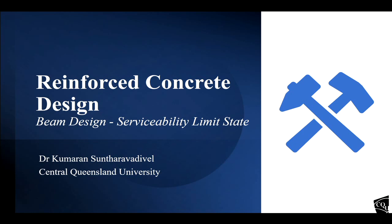Say we assume a 300 millimeter depth or 400 millimeter depth. So we need to assume some dimensions, and then we need to check whether the dimensions are okay. The problem is, if you assume a depth, let's say 300 mil, you assume a 300 millimeter beam, and you start the design, so you put the reinforcement and everything.